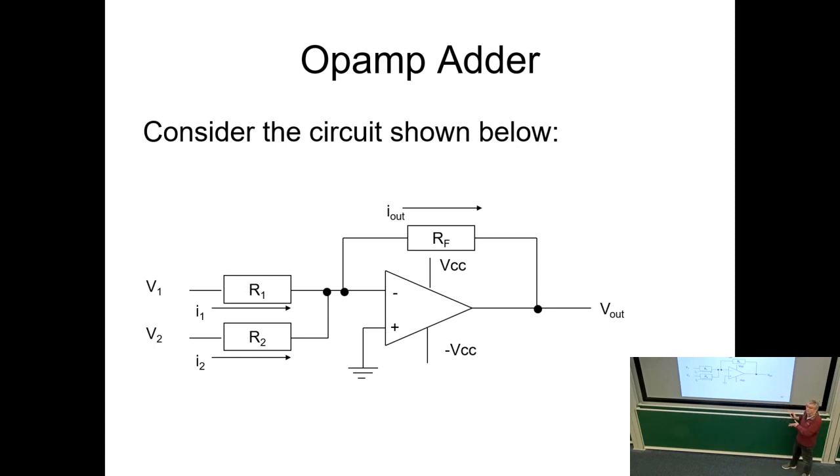When you start looking at these op-amp circuits and you haven't seen them before, you go, right, is there a virtual earth first? Can I justify a virtual earth? If the answer is yes, then suddenly all the linear circuit theory applies, and you can do nodal analysis, you can do superposition, you can do mesh analysis if you want to. And if you want to do it formally, you would then replace this with the model of the op-amp, which remember is two wires dangling and a dependent voltage source at the output, and you can do formal nodal analysis on it if you want to.